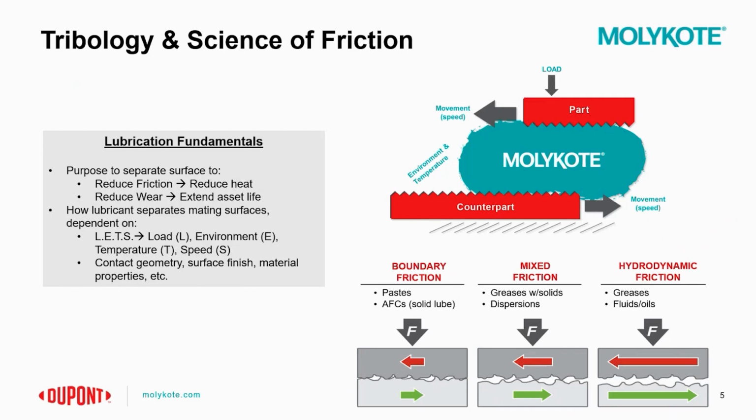For example, the lubrication of a metal flange pipe may require grease with corrosion mitigation additives in order to prevent crevice corrosion in chemical processing or in applications involving upstream oil and gas markets. Additionally, temperature is important to consider as well, because applications requiring a wide temperature range would require the selection of a more premium, high performance enhancing base oil or additional additives as well.